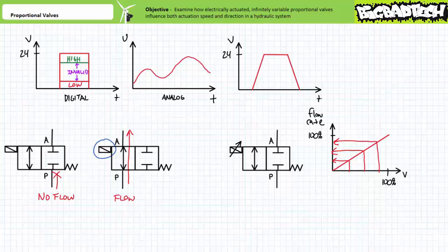Additionally, proportional valves sometimes include sophisticated feedback mechanisms that allow them to not only receive an input signal, but also send an output signal that can be monitored by a control system to perform incredibly stable, precise, accurate, and repeatable movements of an actuator despite a changing external environment. Not sure if you can tell or not, but I'm getting kind of excited here, because proportional valves blow wide open the doors of many advanced topics, including open and closed loop control, PID control, and more.